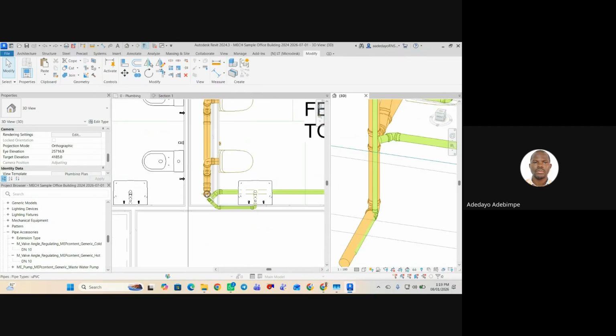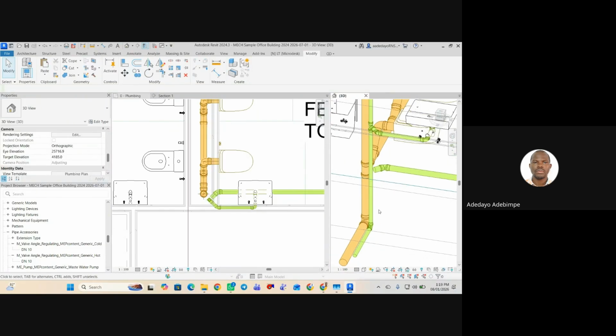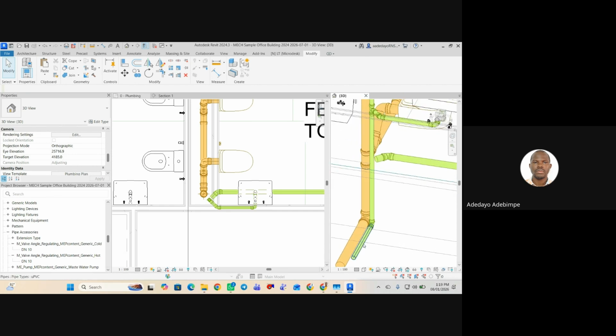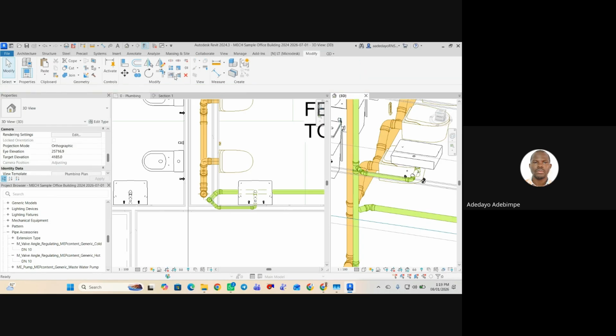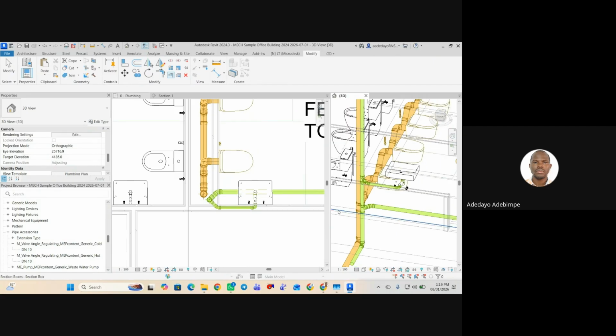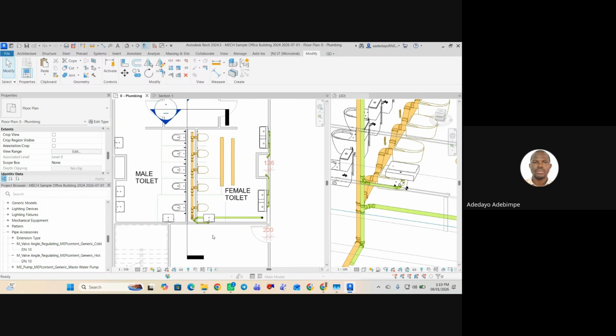So let me just shift this guy a little to the side, just to ensure my pipes are not clashing. So in 3D view, tab, select, then click on this fitting, and change it to 70 mm. So let me try my trim extend again. Select and select. Now we are connected. Now we have our floor drain as well.